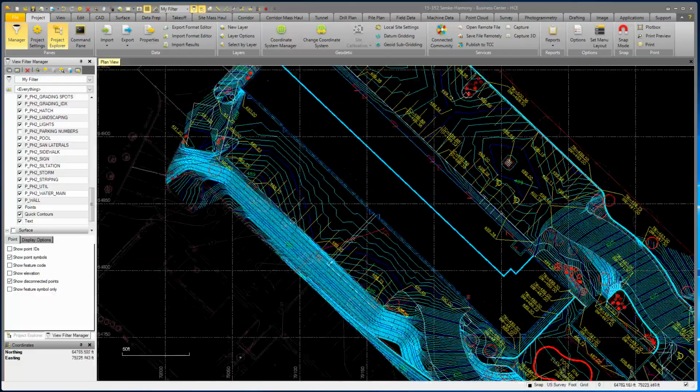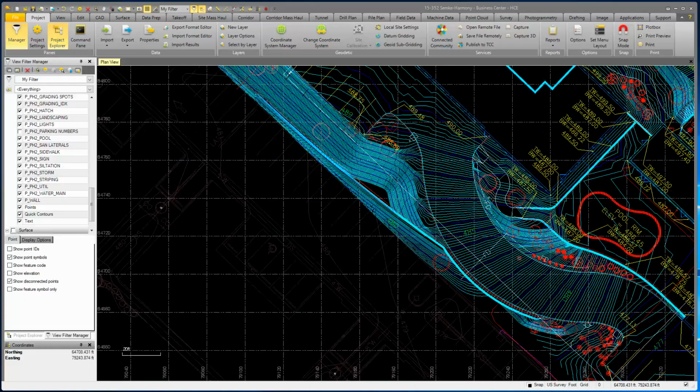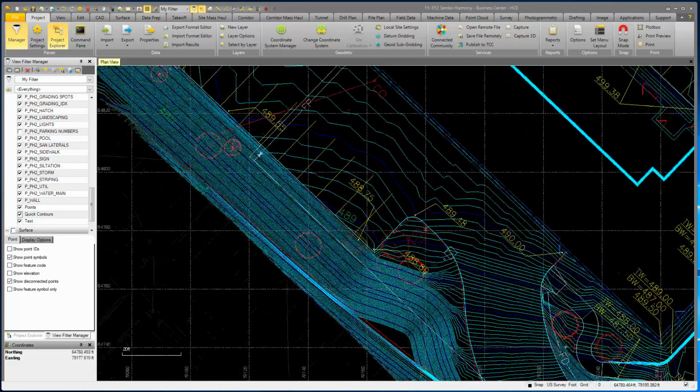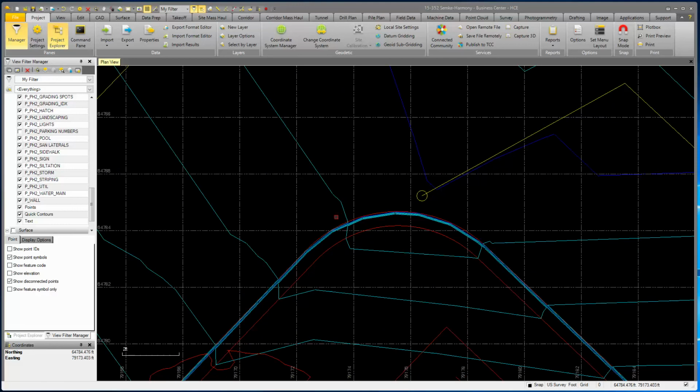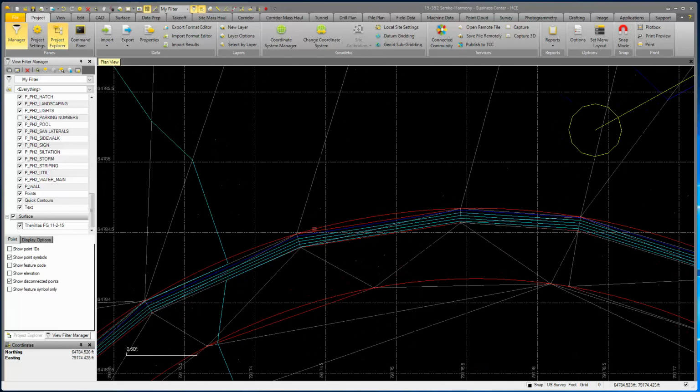So that's approximation settings. The other one is the actual setting of 0.05, 0.05 around a horizontal and vertical curve, is how it sets when you go around an arc. So we have a 3D set here, and if we change the settings, let me turn the surface on. So it looks at the approximation. What that is, is the distance from this arc to the straight line segment. That is the horizontal approximation.